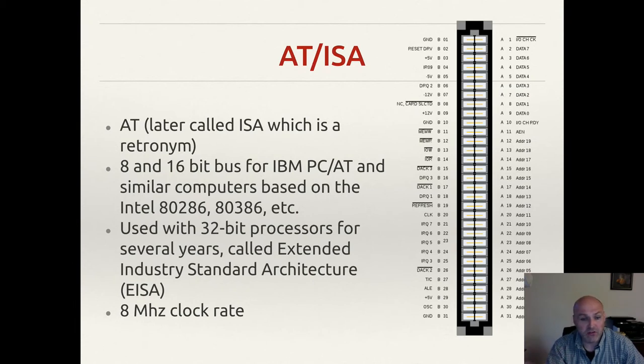It was an SX20, which meant that the processor ran at 20 megahertz, but the system bus, as seen here, only ran at 8 megahertz. So there were different clock speeds, which is still common today, between the CPU and the system bus. The system bus controller was operating at this 8 megahertz rate, and your CPU was operating at whatever rate it was.